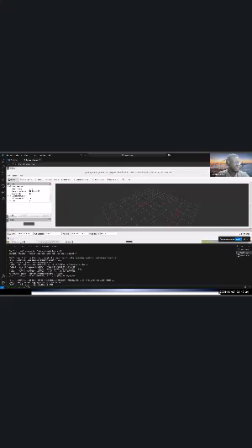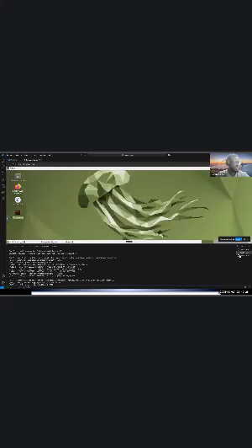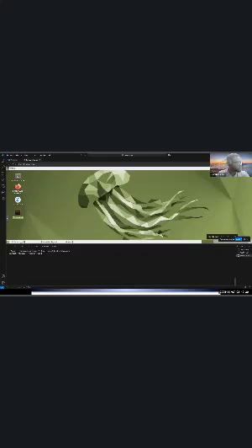We're going to echo the scan topic. The command is simple. What we're going to press is ros2 topic echo, slash, the name of the topic is scan. Okay, scan topic now. What can I do is ros2 topic list, because I probably missed the topic name. You can see the list of topics. You have cmd_vel. cmd_vel is what we used to drive the robots with the arrow keys.